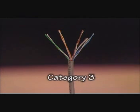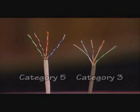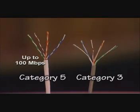Category 3 cable, or Cat3, is used for medium-speed communications up to 10 megabits per second over distances of up to 100 meters. Category 5 cable, or Cat5, shown here with Category 3 for comparison, is used for high-speed communications up to 100 megabits per second at distances of up to 100 meters.